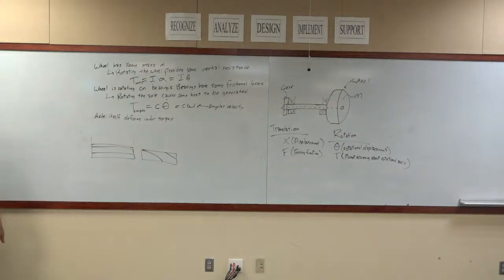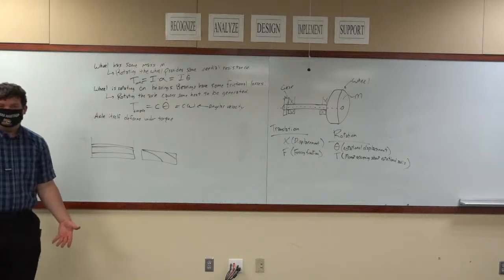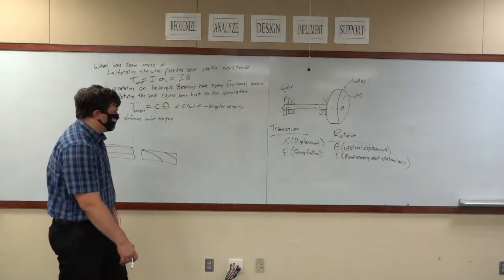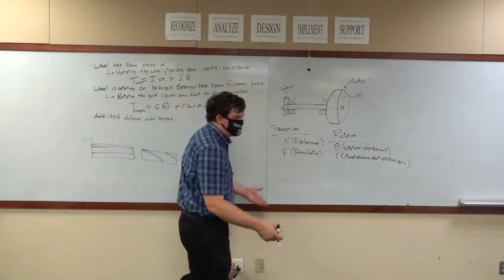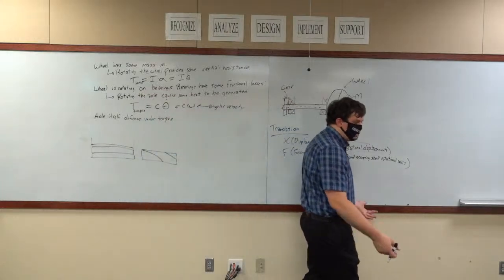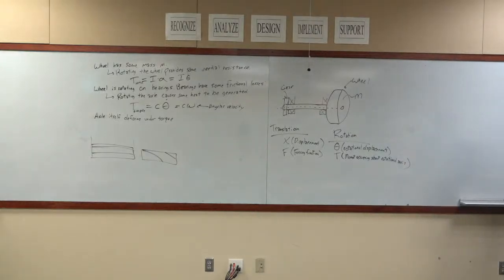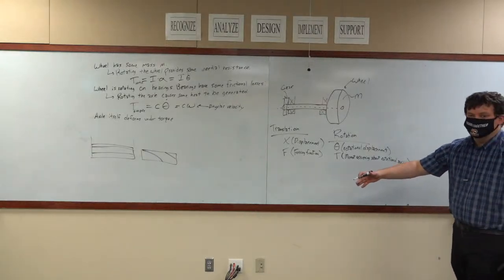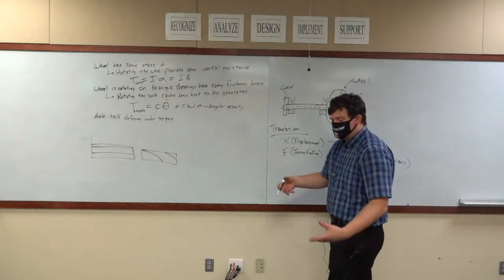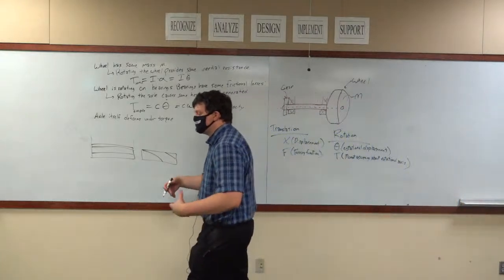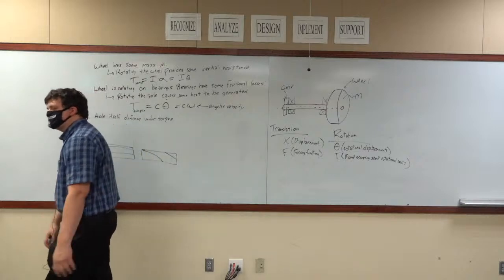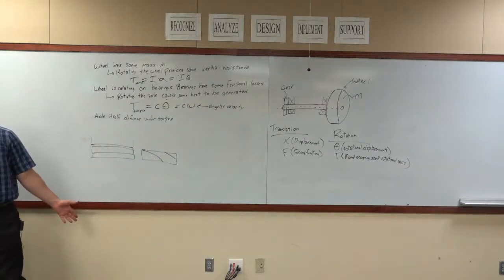If you ever walked across soft carpet, it deforms under your feet, it acts as a spring. Everything, when you apply a force or a torque to it, behaves like a spring. Doesn't matter if it's concrete, doesn't matter if it's steel. You walk across a steel I-beam, it is behaving like a spring. It is absorbing your energy, and it is absorbing it through deformation of the material, which is the definition of a spring.